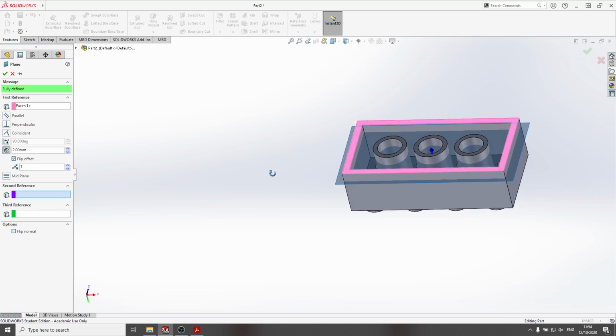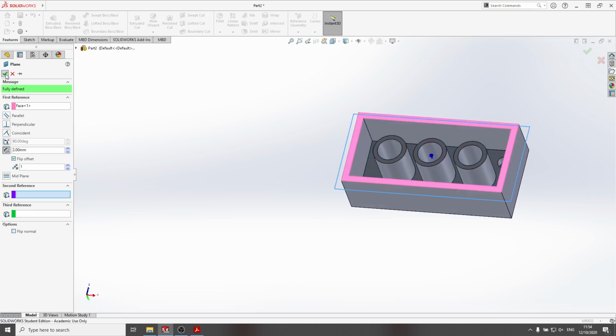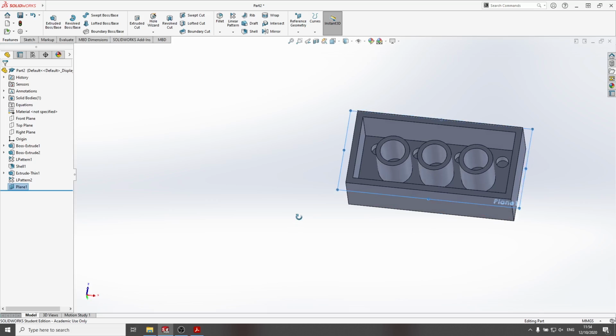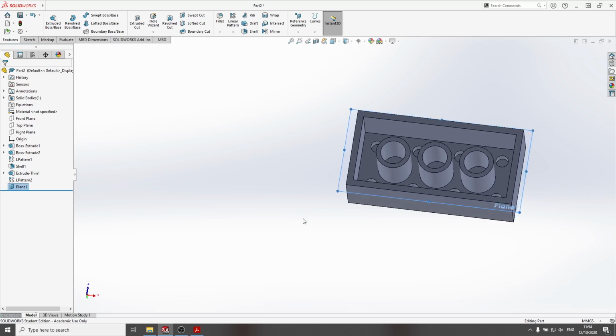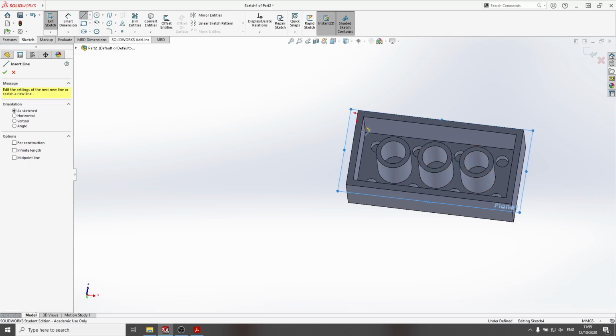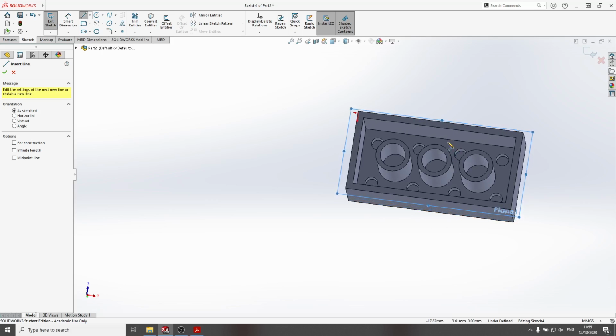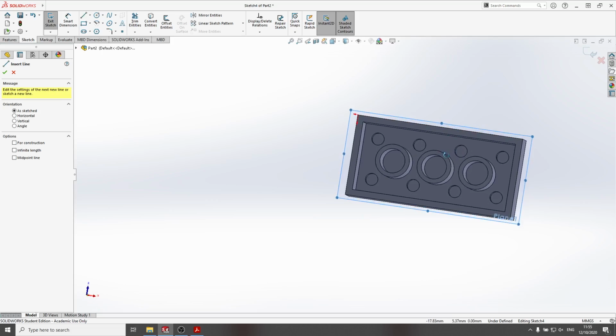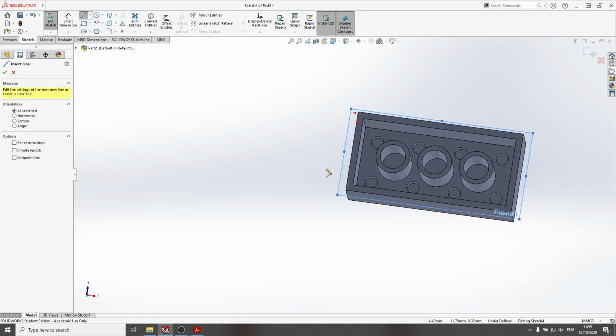So in that plane I want to draw the rib. And ribs are working in a maybe surprising way. I just need 2 lines to define the rib here in that case. So I say I have selected that just created plane, click on sketch, want to create a line, and first of all what I want to do is, sorry, I have to do something else in between.